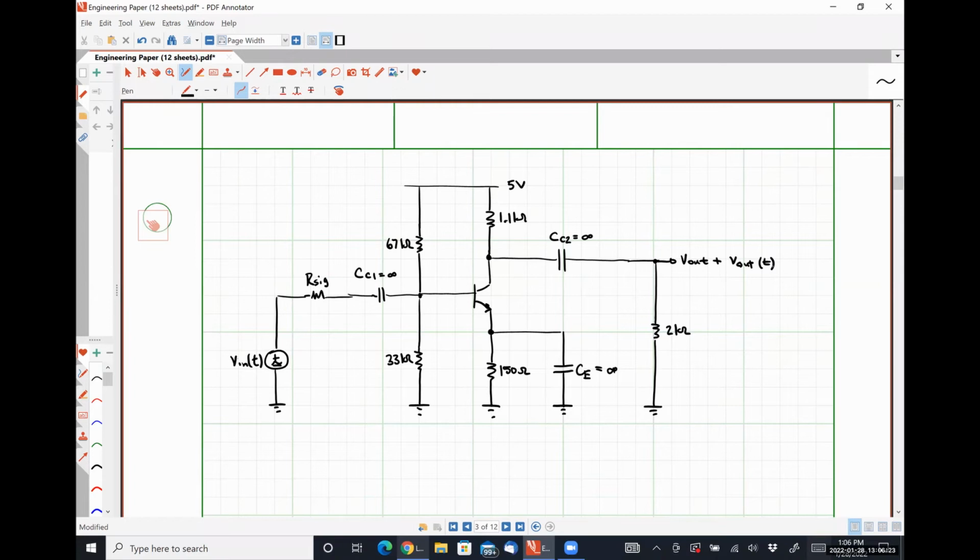So again, this is an open circuit for DC and a short circuit for AC. That is actually a reasonable way to think about it, but slightly different. So if we're in transition, if we're in like intermediate frequencies, so we're a little bit below where we want this guy to operate, or if we're a little bit above in frequency where we don't want this guy to operate, it absolutely does behave as a filter. But effectively what this guy does is prevents the load impedance from influencing the biasing point, right? So at DC, when this capacitor is an open circuit, the load is disconnected.